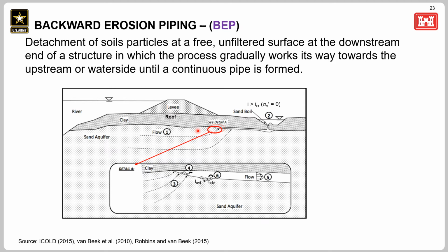BEP can initiate and progress at gradients likely to occur within an embankment or its foundation. Later this week, we'll hear a case history of Wapapello Dam as an illustration of BEP in the real world. This graphic shows the BEP process.